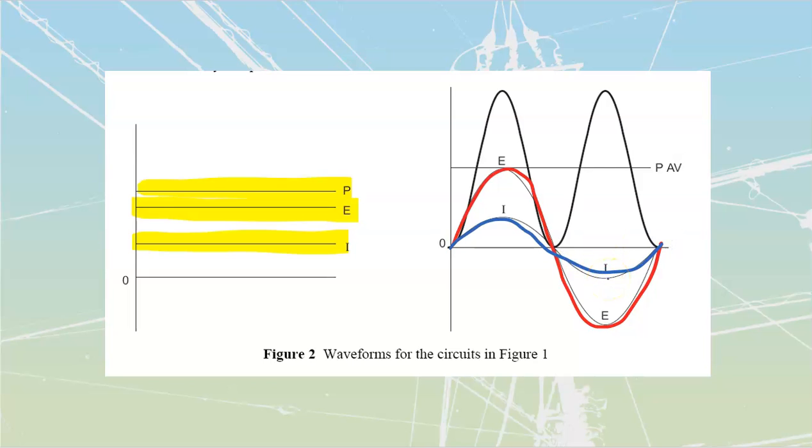And we also know that my power is simply a multiplication of my volts times my amps. If I multiply these amps and these volts together, I come out to this total amount of power that is going to be up like this. You multiply them together down here, they start building power, you multiply them together, we hit this peak. It peaks with these two at the same time, then it drops back down to here. And then over here, we now go to a negative current and a negative value of voltage. Once again, going back to simple base math, a negative times a negative is equal to a positive. So if we have got this over here, it's just simply because we're taking a negative times a negative.